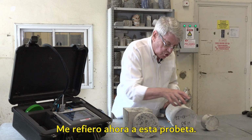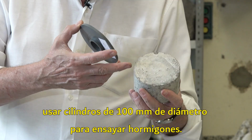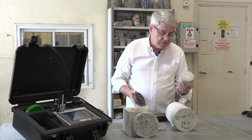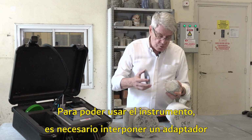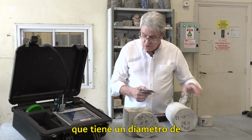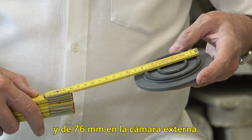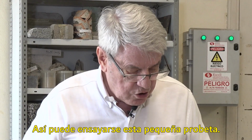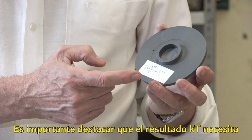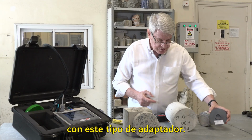I will refer to this small sample. It's very common nowadays to use cylinders of 100 millimeters diameter for testing concrete. In order to use the instrument, we have to interpose an adapter which has a diameter of 38 millimeters in the inner chamber and 76 in the outer chamber, in order to be able to conduct the test on this small sample. It's important that the result needs a correction by a factor of 1.73 with this type of adapter.